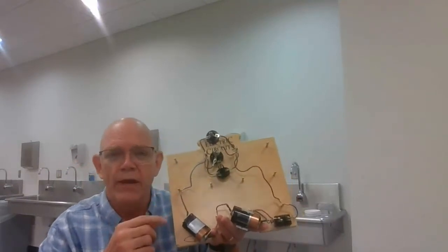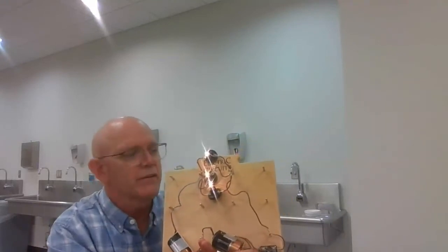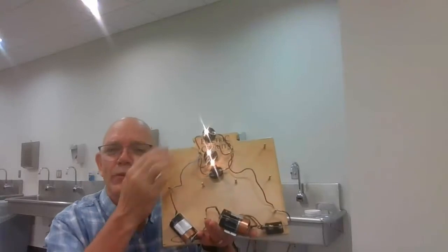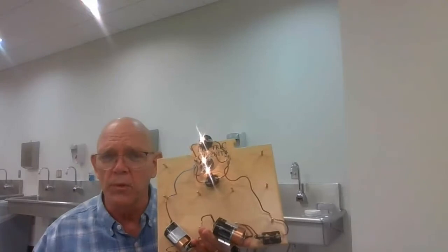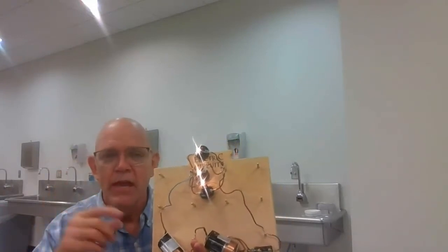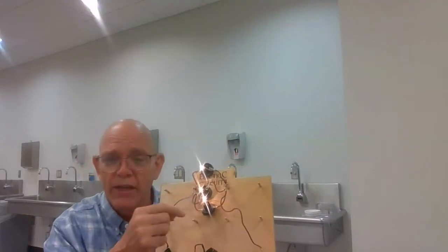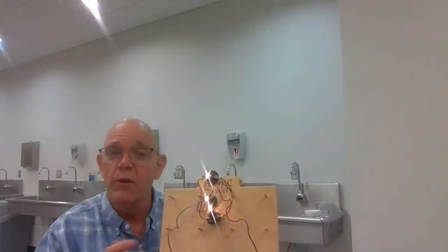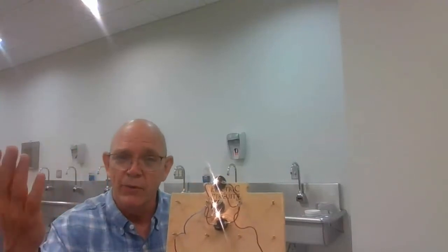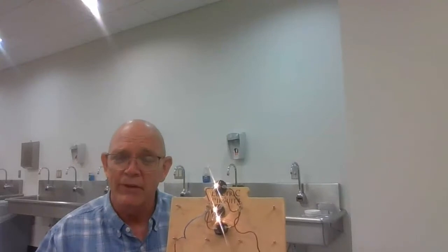Okay, so let's see what happens with our lights when we turn them on. We put our switch down. And now good, I made sure I had it all connected right. Notice that all three of them are on. And are they bright? Yes. In fact, they're all just as bright as when we had just one bulb in the series circuit. That means that each of these bulbs is getting 3 volts. Now, if these identical bulbs have exactly the same resistance, then they will also have the same current, because they're getting the same voltage and have the same resistance, so they're all getting the same amount of current.